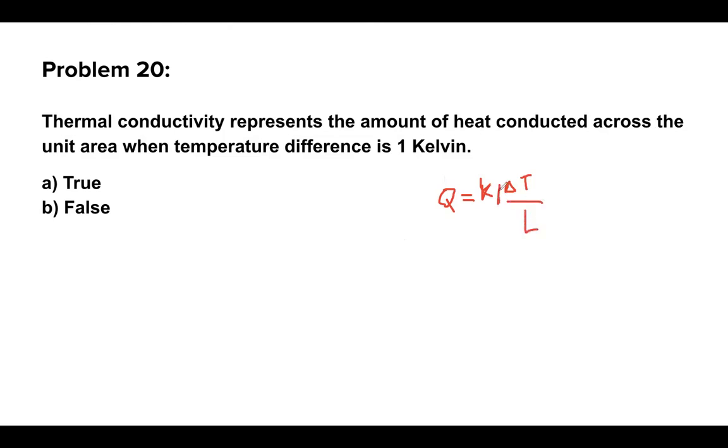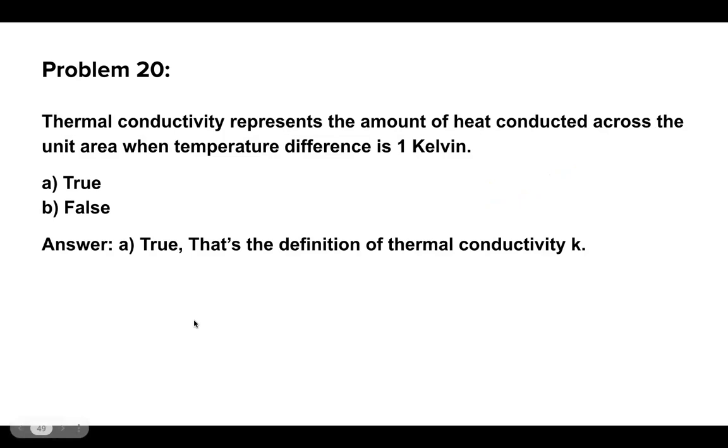Sorry, the area was there. Sorry for that. So if this A is unity, the temperature difference is unity, the length also unity, then k is nothing but the amount of heat conducted. So that's the definition of k. So the answer is true, because that is the definition of thermal conductivity k.